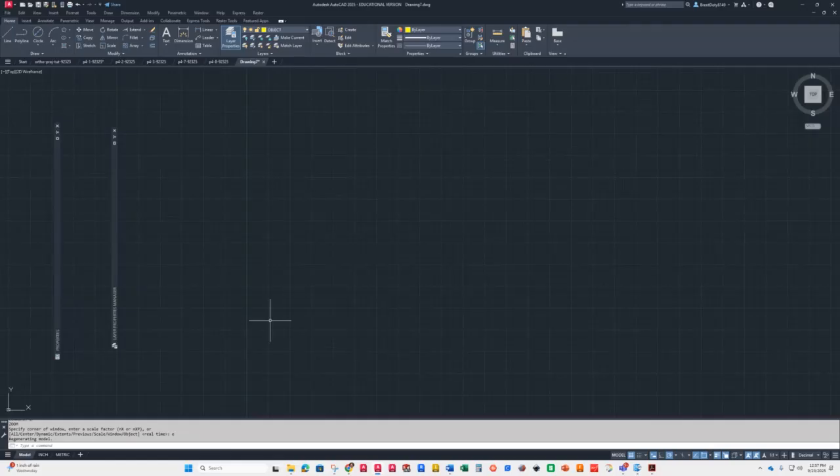Well, if you don't change the limits, it won't let you draw outside of a certain size. It'll quit letting you draw. It defines the area for AutoCAD so that zoom works right, and it basically tells AutoCAD, okay, you want to use this much space, so this is where I can zoom in and out with no issues, and I can draw in this area.